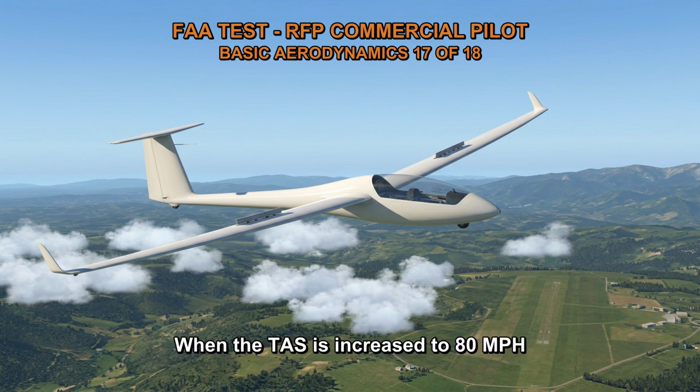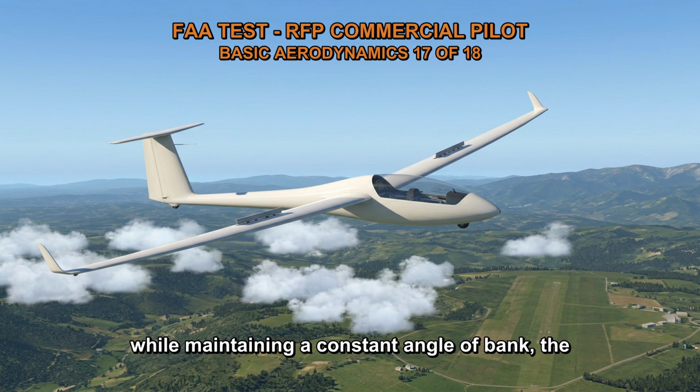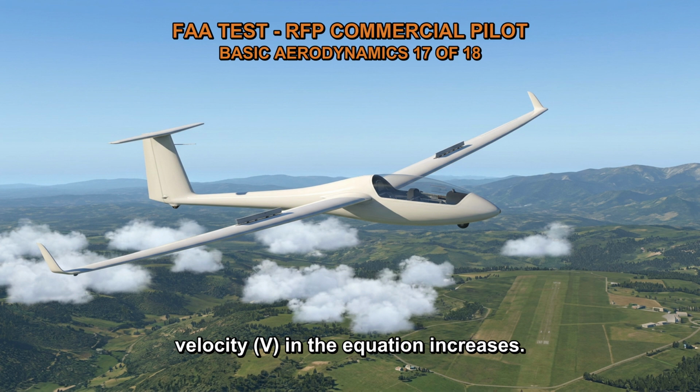When the TAS is increased to 80 miles per hour while maintaining a constant angle of bank, the velocity, v, in the equation increases. To maintain a constant centripetal force and a constant angle of bank, the radius of turn, r, must increase.